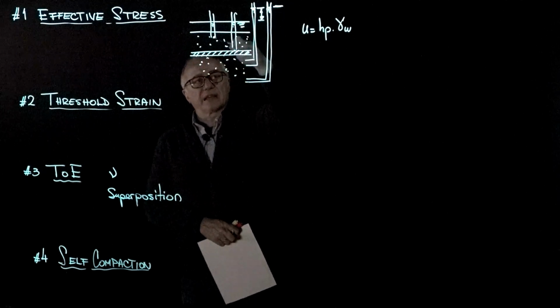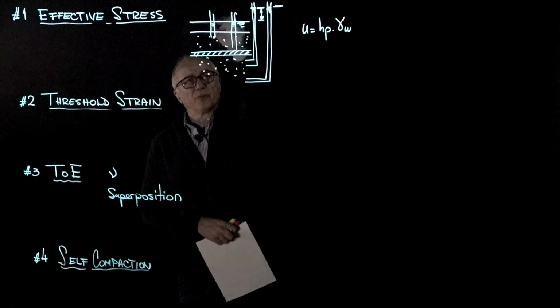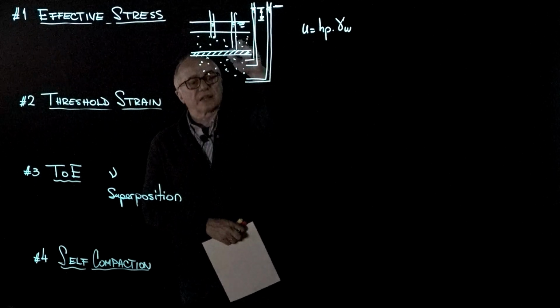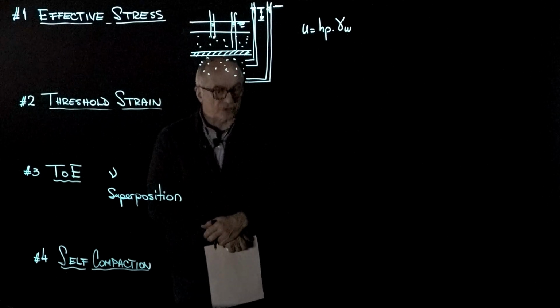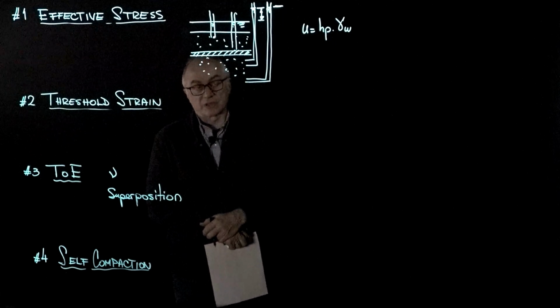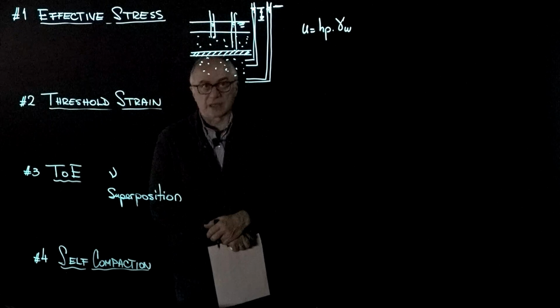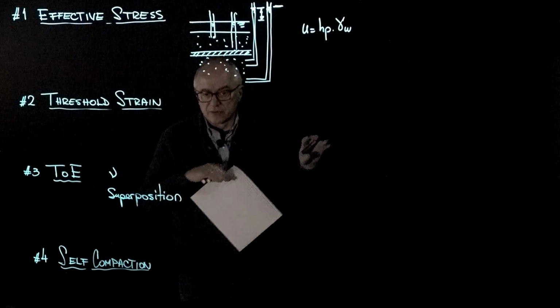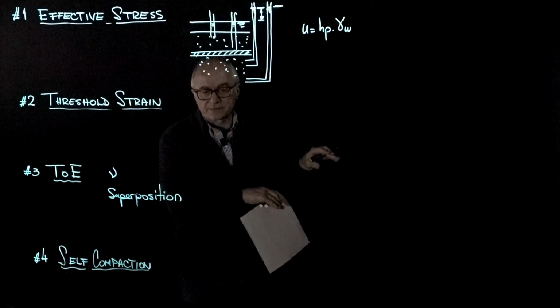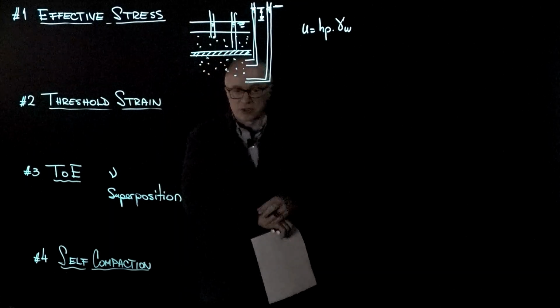Immediately above the aquitard it will rise to the water table, and therefore the aquitard is indeed subjected to a significant pressure difference, which will tend to drive fluids through the aquitard. This is the case as well for seal layers, for petroleum, for oil and gas, for CO2 geological storage.